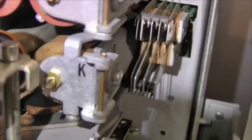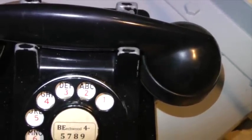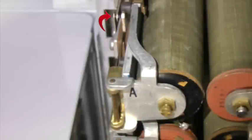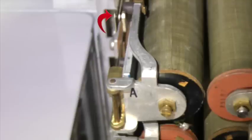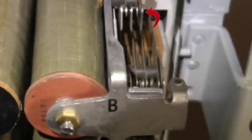The connector remains stable in the connected stage with the A, B, D, F, and K relays remaining operated until the end of the call. When the calling station hangs up at the end of the call, the release sequence begins. With the handset back in its cradle, the loop through the telephone set is opened, and so the A relay releases. This releases the B relay. B released removes ground from the incoming sleeve lead, which causes the entire preceding switch train to release.